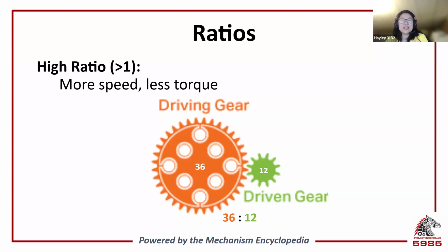When it comes to the decrease in torque, we can think back to how gears are essentially just a bunch of spinning levers. When you're analyzing where that energy goes, we look at the formula for work, where work equals force times displacement. This means that for the same amount of work, if there's a larger displacement, e.g. 3 rotations instead of 1, then there is a decrease in force.